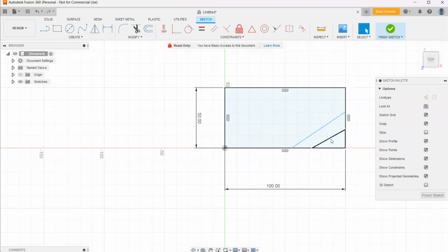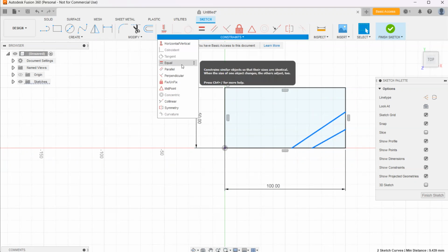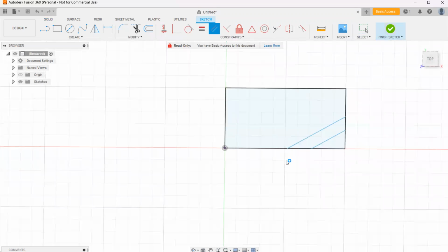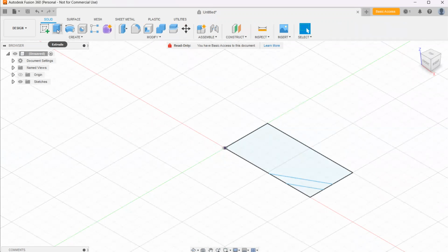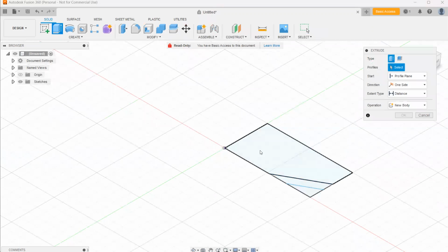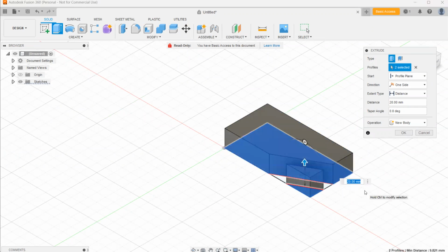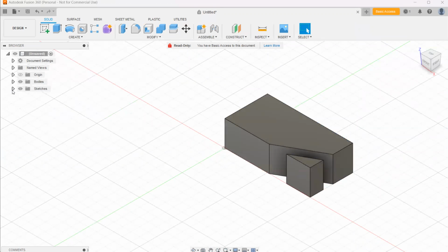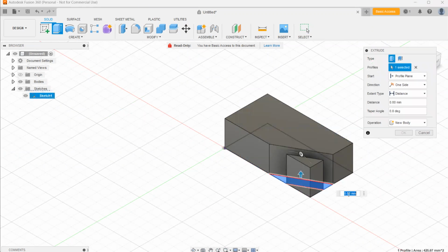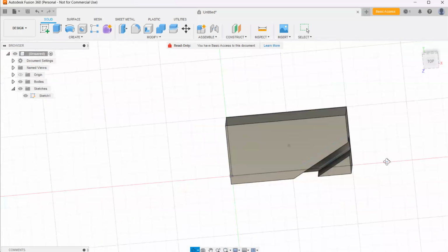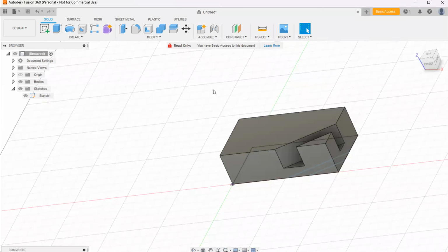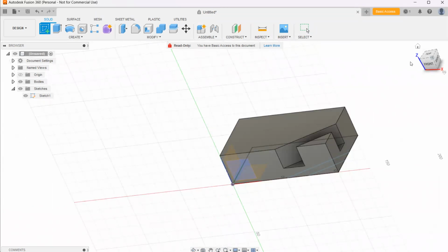We also have, for example, if we want to have the same parallel lines here, Fusion 360 also has, if we choose both lines, those are its constraints, or relations in SolidWorks. We could also make them parallel, finish sketch, and it has the same extrude boss base, but here it's called just extrude. We could select our parts and extrude them, for example, here 30. We could show the sketches, and we could again select this profile to go, for example, at 10. So as we can see, all CAD software would have the same thing, but they will have different names, different looks, and will be somehow different.